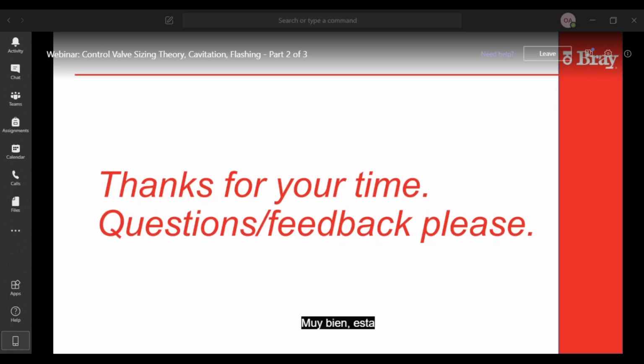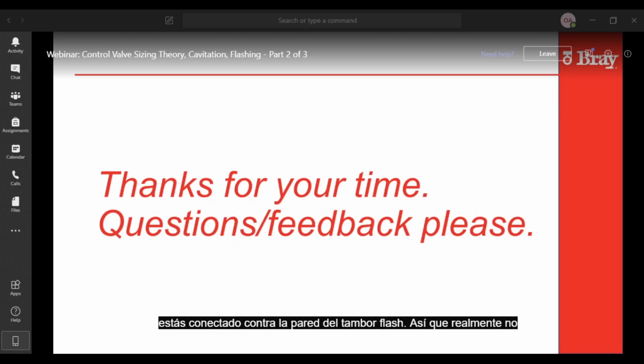All right, there's another good one here by Mr. Anonymous. If you have a valve right by the inlet of a flash drum, would you consider the K = 1 pipe exit and the FP piping factor? So you're basically connected right against the wall of the flash drum. So it's really not a pipe anymore. It's more like an open vessel. So I think at that point, you don't need to be worried about that factor there.